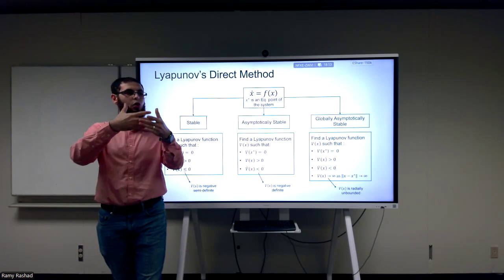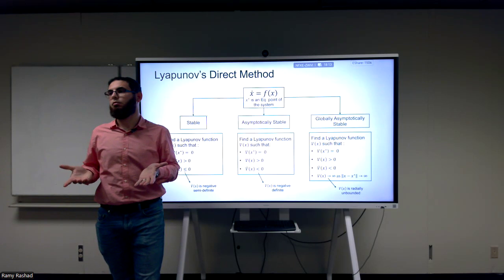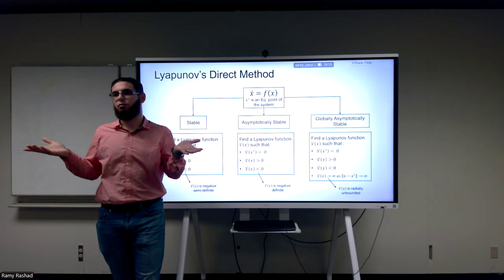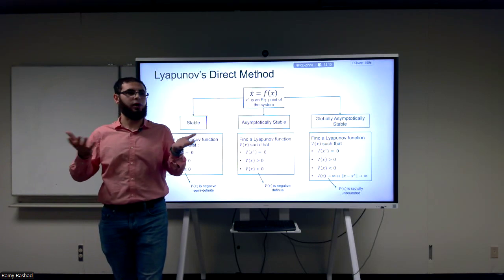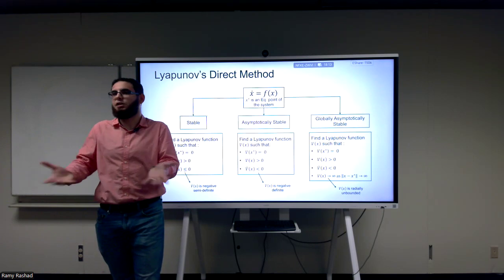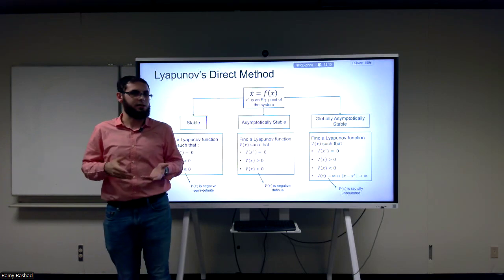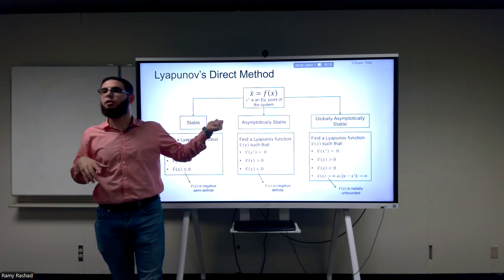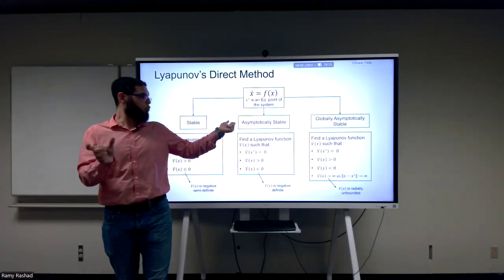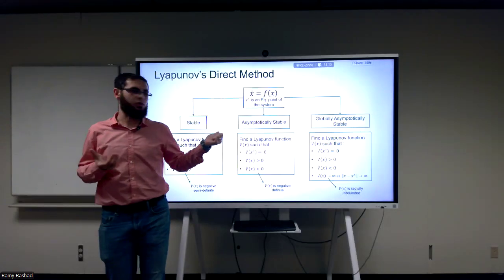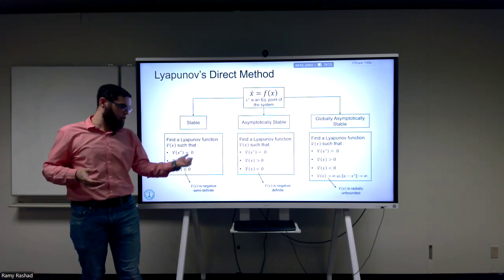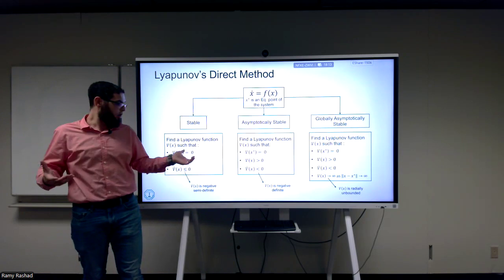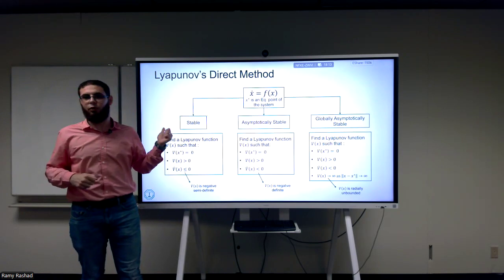When the energy converges to 0, what does that mean? What does it mean physically? If I tell you that the kinetic energy of a system is 0, it means it's not moving, right? It's stable. It's stopped. It's not doing any motion anymore. This is what the kinetic energy means. So this is the idea that Lyapunov came from. But he generalized it not only to work with energy functions, but with any other energy-like function that you can find. And if you can satisfy the same conditions that a mechanical system would satisfy with this mechanical energy, then you can conclude the stability of the equilibrium point.